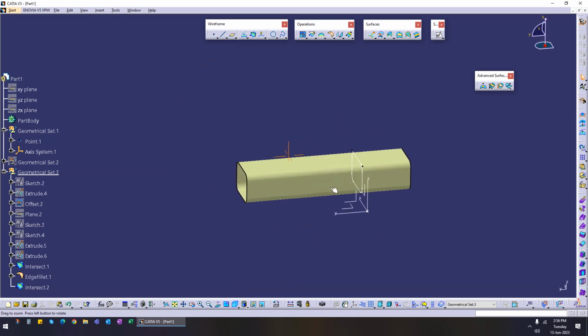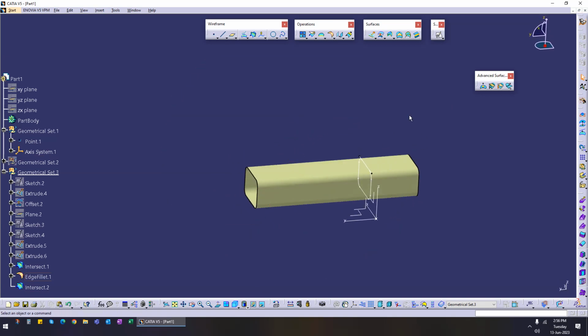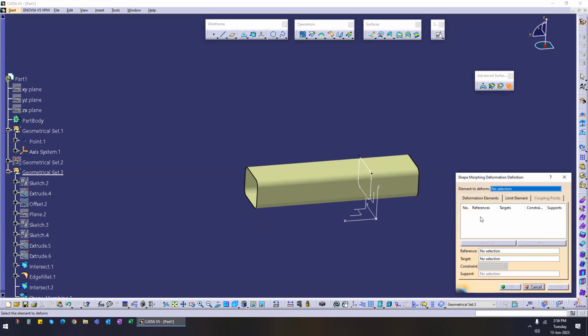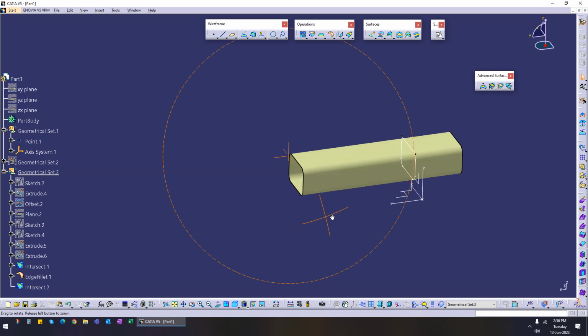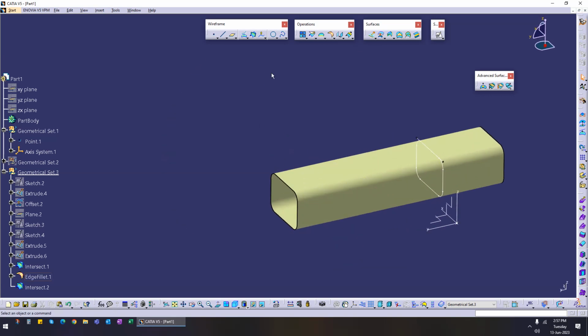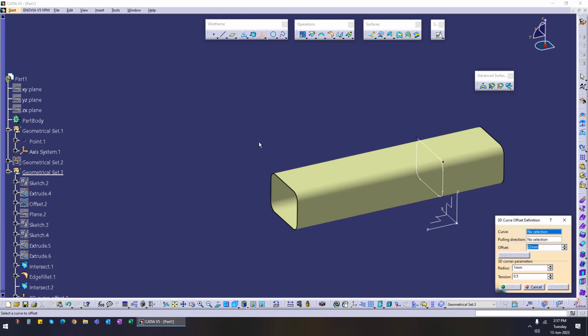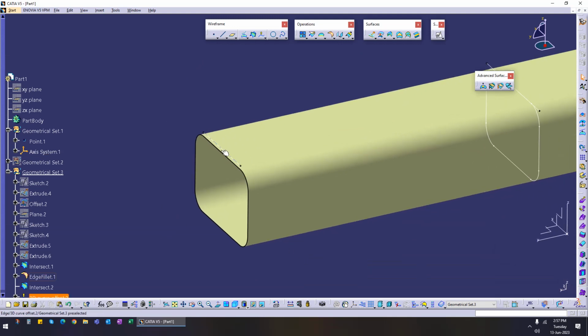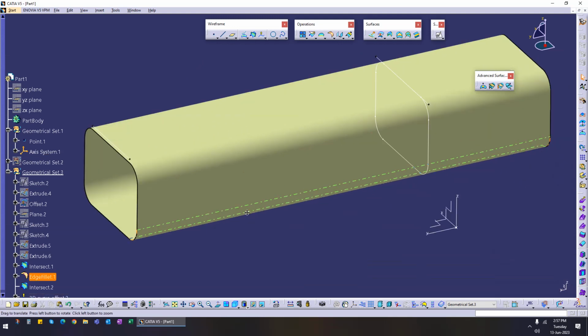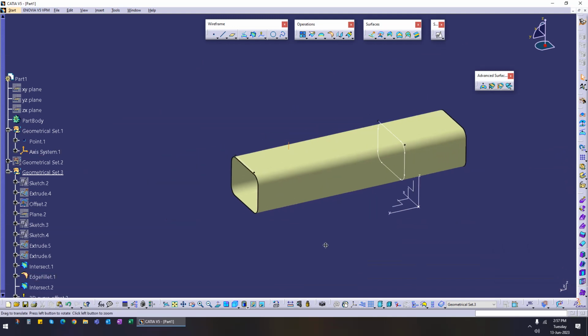And now we need to create some target curves. So here it is saying reference, target, reference and target. So those are the two things we need. So let's create references on this side. I'll make use of this 3D offset, this curve, this direction, 5 millimeters. Okay, and we create. Okay, so this will become our reference, and let's create a target as well.